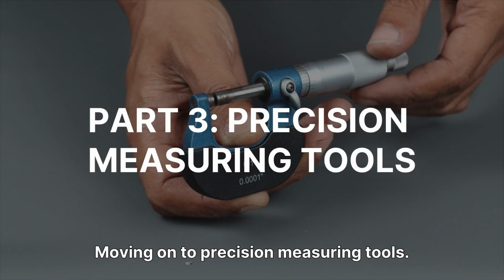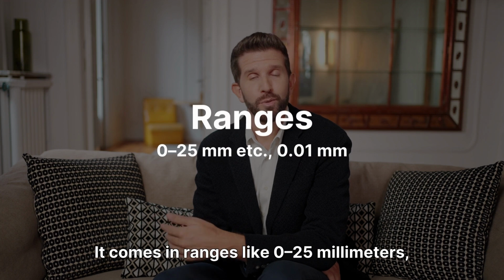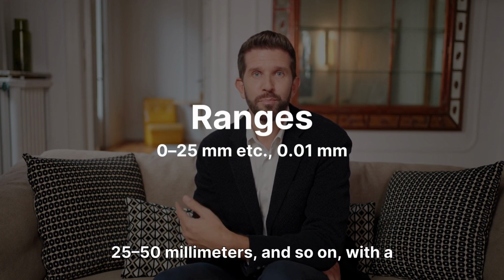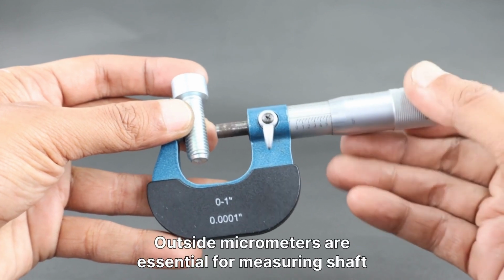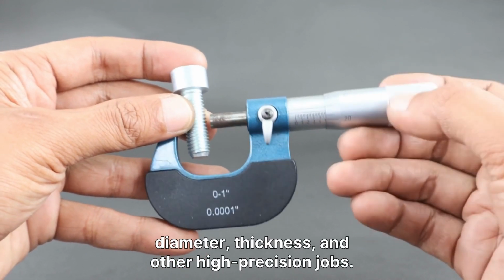Moving on to precision measuring tools. Let's start with the outside micrometer. It comes in ranges like 0 to 25 millimeters, 25 to 50 millimeters, and so on, with a least count of 0.01 millimeter. Outside micrometers are essential for measuring shaft diameter, thickness, and other high-precision jobs.